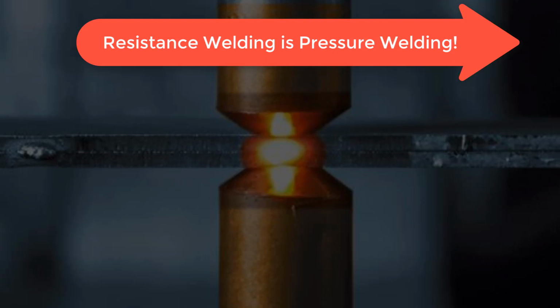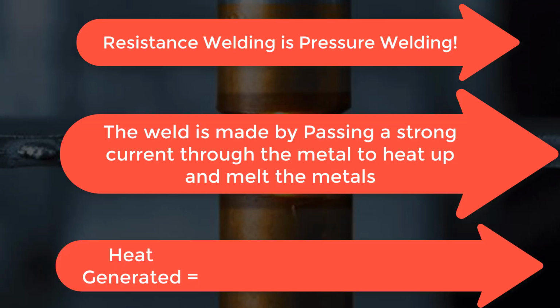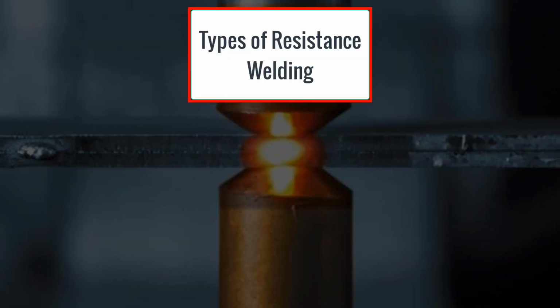Resistance welding is one of the types of welding that falls under the category of pressure welding, and here heat is generated by passing a strong, high intensity current. As we all know, due to the resistance, heat is generated according to the equation I squared R T, right?